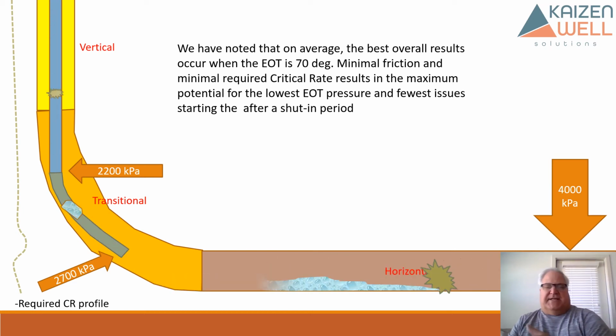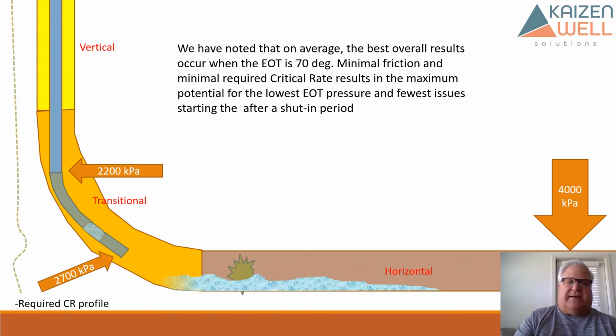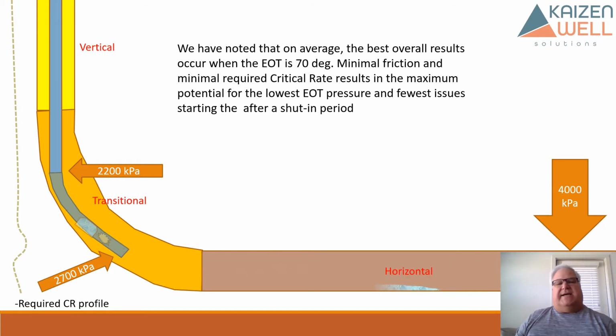Now, as the next slug is moving towards the end of the tubing, the pressure starts to drop, and that liquid that's been pushed or hung up above the end of the tubing starts to collapse and enter the tubing, and so you have this very dynamic undulation of fluid where it's slamming into the end of the tubing. Some of it is carrying up.